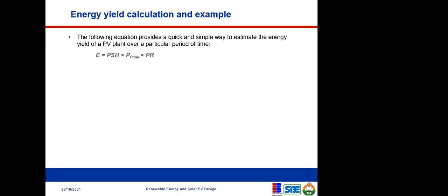It does not mean that the peak sun hours is 8. That is the time that the sun was out. The peak sun hours is when you compress that 8 hours: instead of 500 watts per meter square, you push it up to 1,000 per meter square. How many hours will that sun stay? Can somebody speak to that?